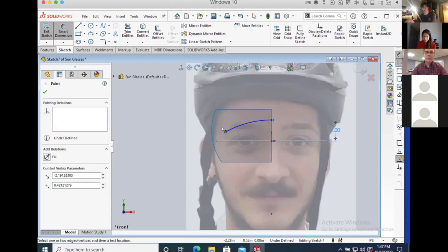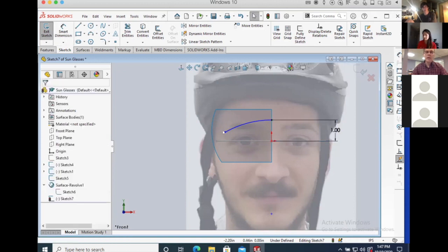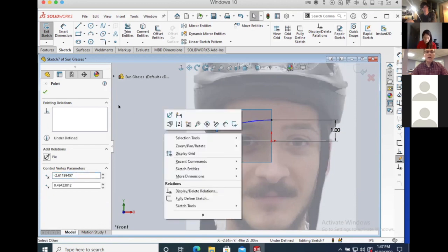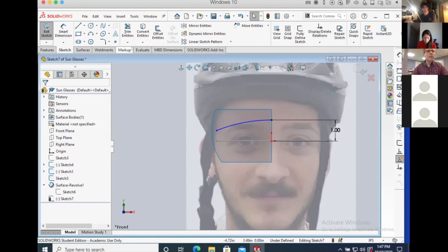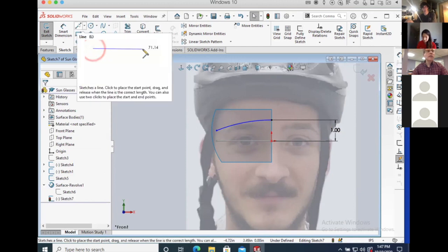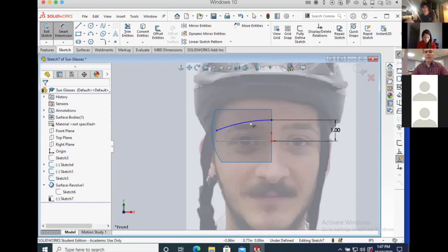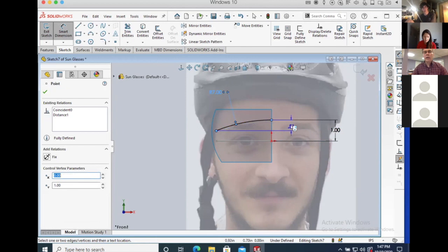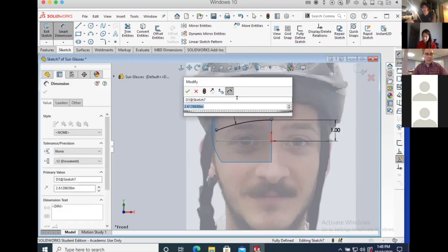So all of that. And this is one where also we're thinking about design intent again. I could put a radius on this, but what's more important to me, at least at this point, is the height. So I want to be able to change the height of this. Actually, I am going to dimension this because I do want to give it a nice round number, like 7. But I'm also going to put on a dimension here to see how much this raises up. Before I do that, I'm going to set how wide this is. Let's go 2.6.